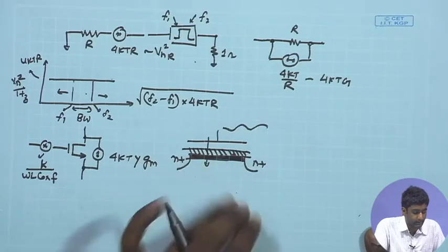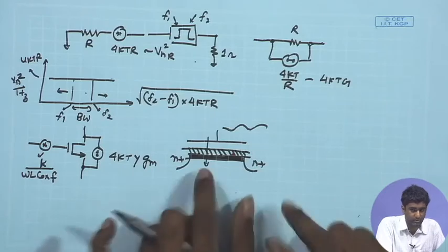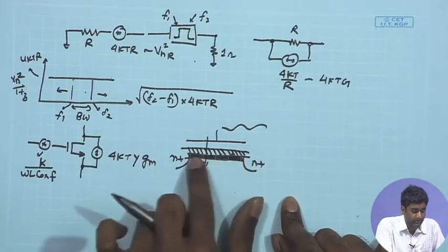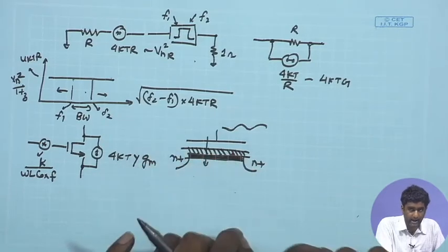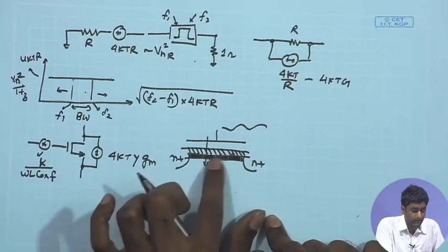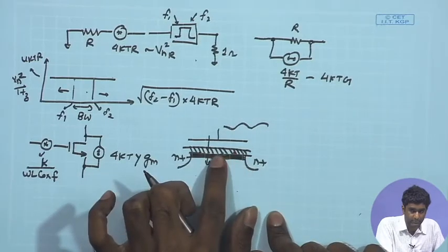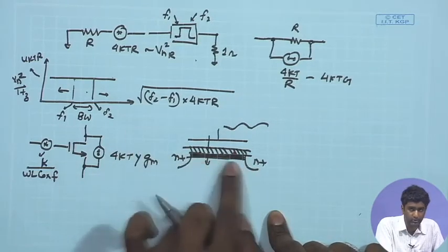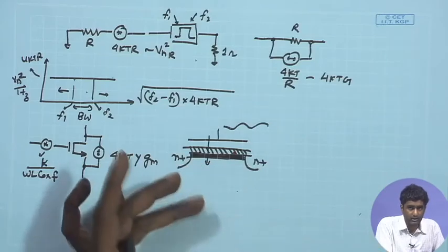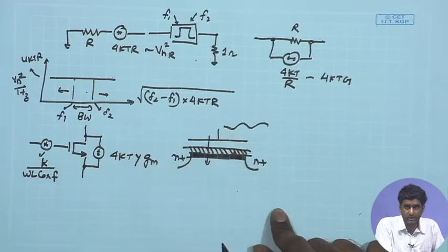As a result, you can see this phenomenon as an effective reaction between the defect states that you have at the interface and the entities which are getting captured, that is the electrons. So, there are two entities, that is the defect states which are capturing the electrons and the freely moving electrons in the channel, and there are reaction constants. The reaction constant, as we can see, will depend upon the applied conditions also.